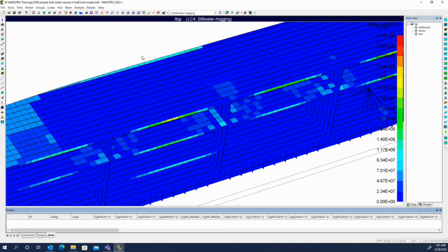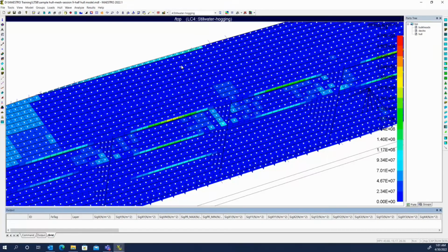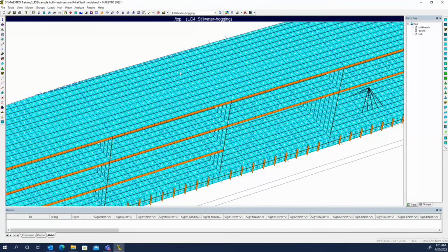So if we turn on directional stress here, we don't see a change initially because everything is still using its own local direction. But we can tell it to define the direction so we can see what's going on, tell it to show the direction. So if we look at each one of these, and I'll switch back to the element view, you can see all of these elements have the X direction, the local X, in the transverse direction. These ones we were looking at on the edge are longitudinal, and we can align all of those very easily by just saying define direction.